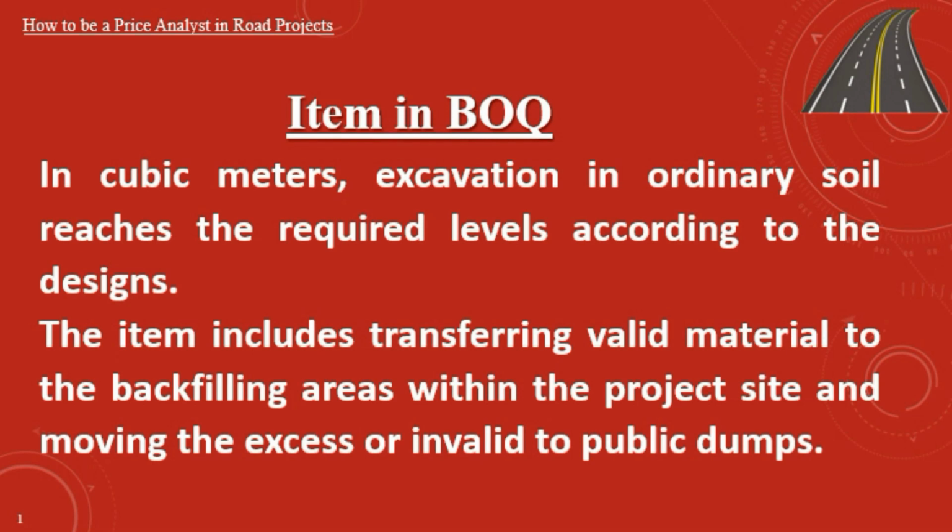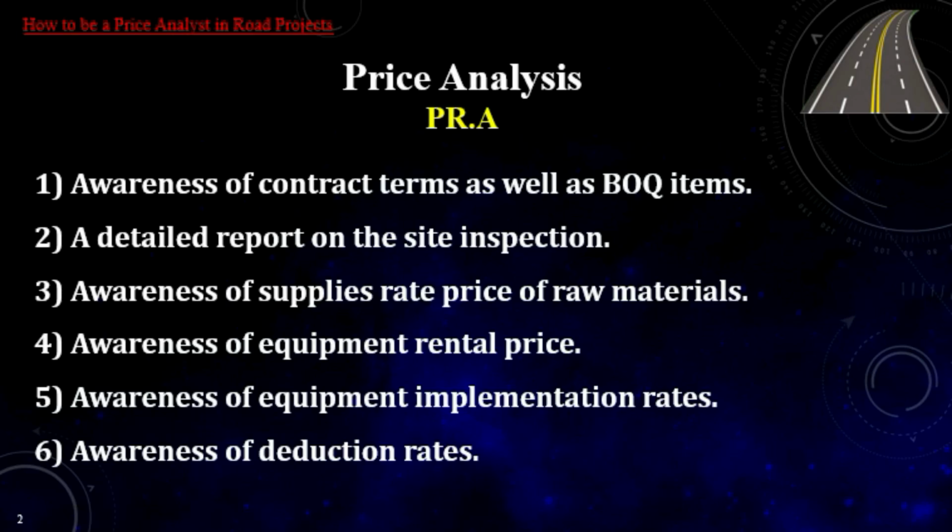After lessons in lectures 1, 2, and 3, we can say that the pricing engineer is ready to start pricing after getting all relevant data: a clear understanding of the contract and all tender documents, a perfect familiarity with the inspection report, a list of all supplies price rates, a list of all equipment rental price rates, actual awareness of equipment implementation rates, and final awareness of official tax or deductions and the agreed indirect cost and profit percentage.